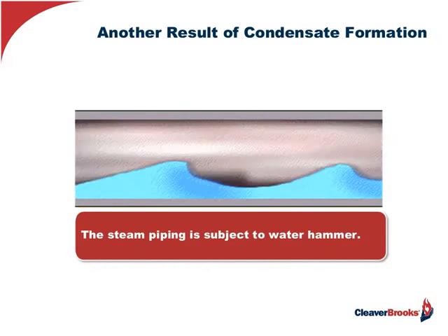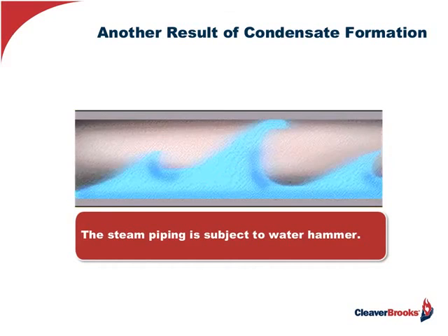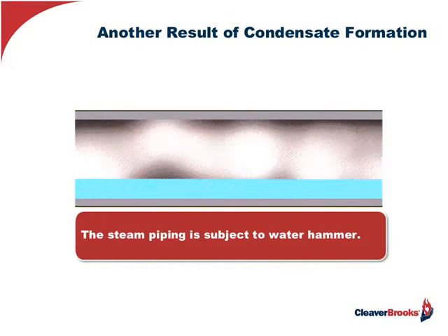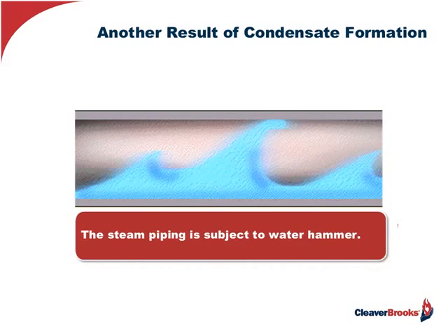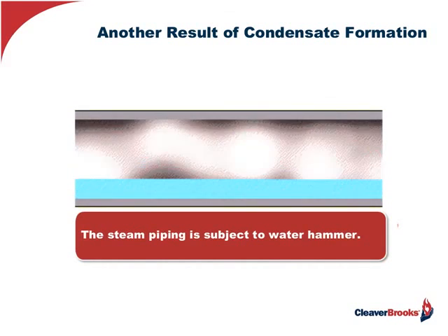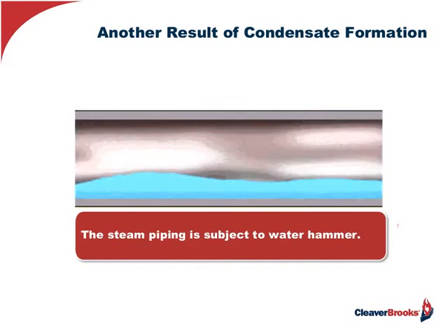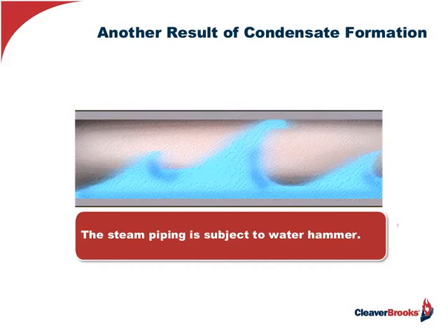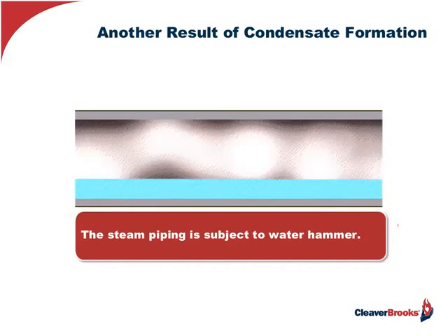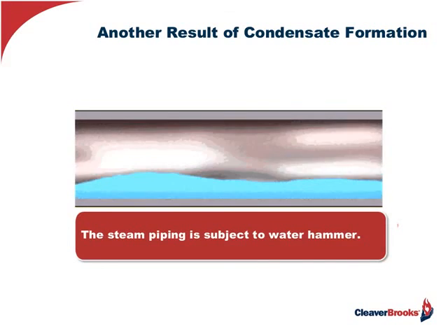So what you see happening right here is, let's assume for a moment that we're starting from a cold start, a section of piping several hundred feet long. After it's been down for repair, because there's been some leaking flanges or a trap replacement. Now, we're in a hurry and under considerable pressure to get the system back up to support production. So we took a shortcut, and we didn't properly vent and drain the section that we were repairing during the warm-up. We just put the pedal to the metal, so to speak, and just let it go.